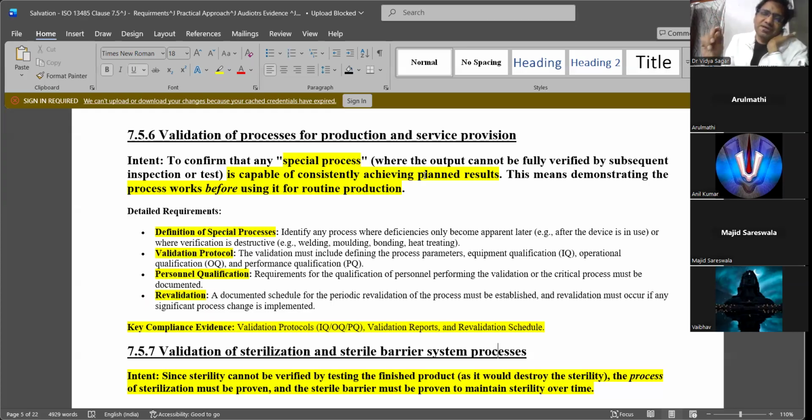I'm looking at only one variable, the ID, the inner ID of the tube, 0.2 mm. But there will be a lot of other things, like what is the roughness of the tube, what is the OD. You need to pick up 6, 7 things and see what are the rejections. So it's very difficult, I know, to achieve 6 sigma. I told you sometime.